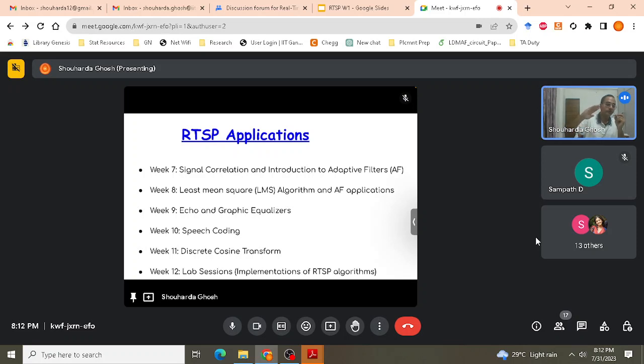By signal statistics we'll be concerned about the mean of the signal, the variance of the signal, some kind of a correlation measure, because of which we will be teaching signal correlation before that. Those kinds of statistical measures will be used to change the filters on the fly. And a fun fact for you, adaptive filters are also a kind of machine learning algorithm. In fact, if you know about machine learning algorithms, it's a kind of supervised learning algorithm. We will have some desired signal, and based on the desired signal we will try to adapt the filter coefficients so that our input signal is processed and adapted to get the desired signal performance.